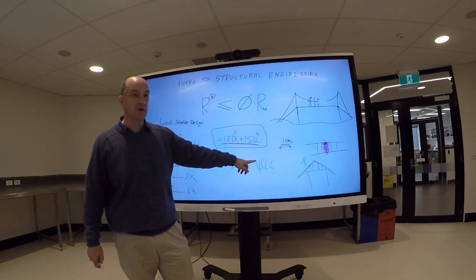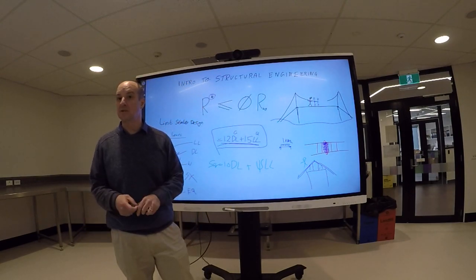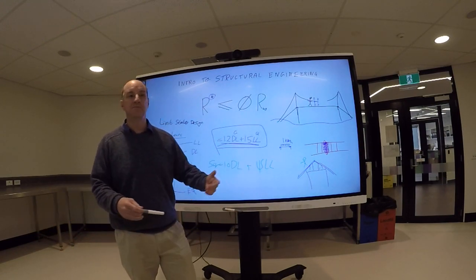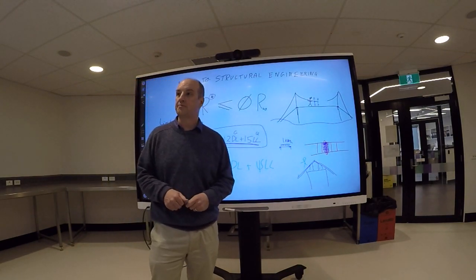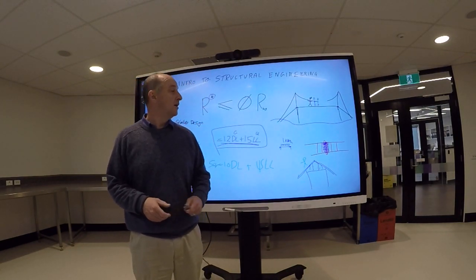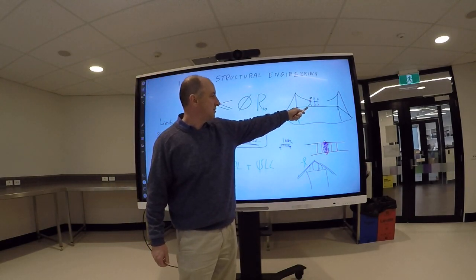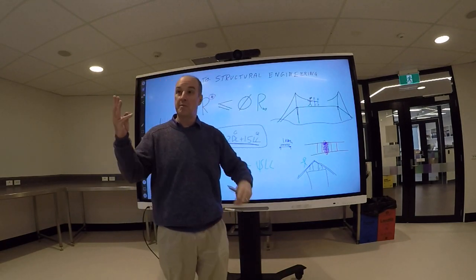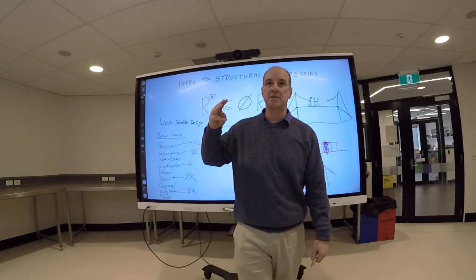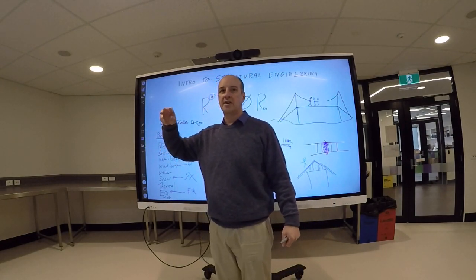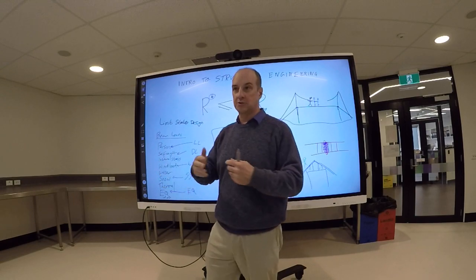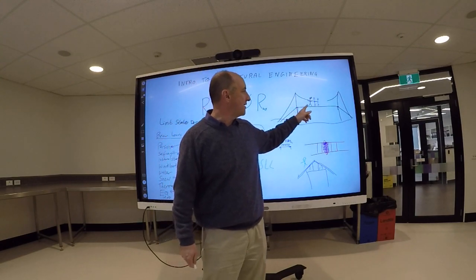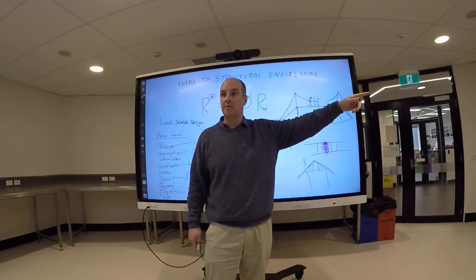So for serviceability, dead load plus a portion of the live load is the serviceability limit state. And that portion depends on the use, whether it's a building or whether it's a bridge or something. So specifically for this bridge, the one that I'm designing is a bit like that. The bridge has got a nominal load limit of 3 people on it at once. So I'm designing the serviceability for 3 people so that it's not going to bounce or deflect so excessively that they can't cross it. But actually the strength limitation is a person every meter on that bridge, and it's an 80 meter span bridge.